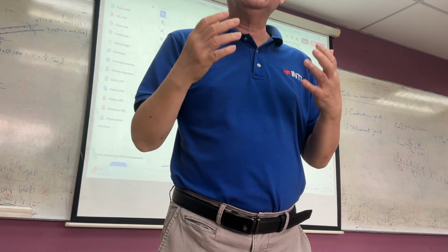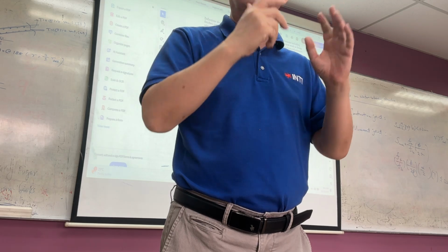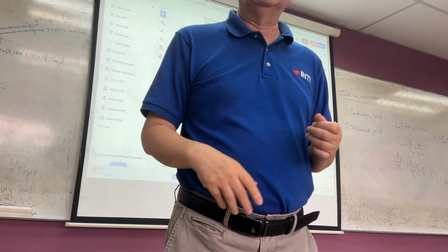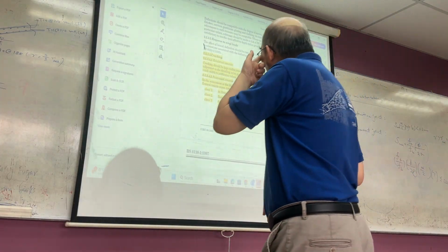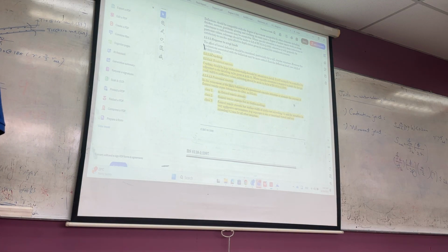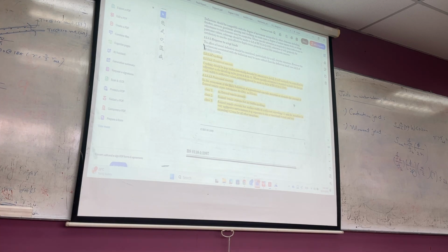But it's just that it's not visible to your eyes, because we control the cracking in such a way that it's not visible. But nonetheless, if you put water through it, it will seep through. So that is why for reinforced concrete in the bathroom, we have to make it waterproof. They put the tilings and so forth. Of course, the swimming pool, right? Because the water, there are cracks there. It's just not visible to your eyes, but the water can seep through. Alright. So part 2.